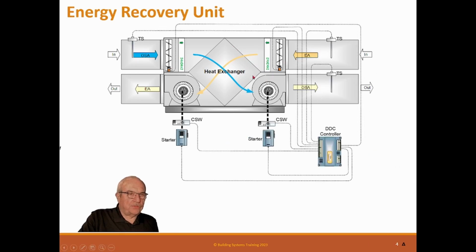So it's very important that this filter be there and that it be kept maintained. It has a simple control system: two motor starters. Normally these are constant volume devices, so the fan runs at a constant speed all the time. They can be variable volume, which is a more complicated system, but normally they're constant volume. As it draws the exhaust air, which can be coming in from just grills, or can be other exhaust fans blowing into this system, the system is just taking up the static pressure, and the exhaust systems go through. The supply air is drawn in through this fan and normally pushed to other air handling units as their outside air intake. Standard makeup air unit, and of course the whole purpose of the unit is for energy economy.